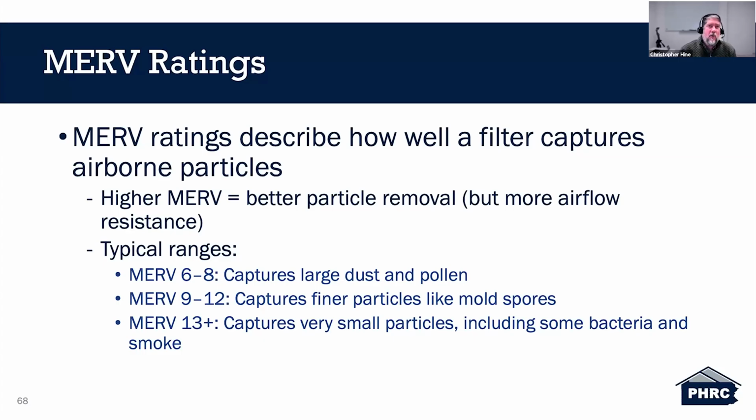One thing I want to mention is that you can't just automatically take an HVAC system that has a 1-inch cartridge filter designed for a MERV 6 and immediately put in a MERV 13 because you want better filtration.